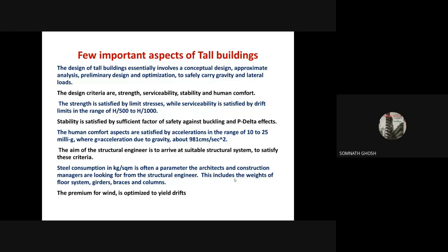The design criteria, basically, are strength, obviously, serviceability, that is the deflection, stability, obviously, and human comfort, which I was telling you: if you construct a building that is structurally safe, stable, but that particular building is undergoing a huge drift, huge displacement at the top, then nobody can stay there.